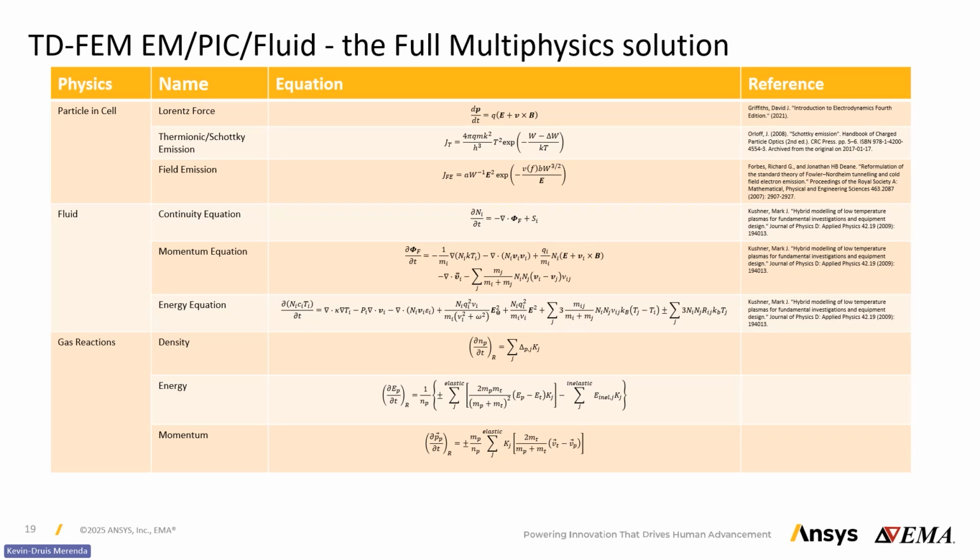So we can do that with the PIC and the fluid solver. The fluid solver is a continuum, so we don't have to worry about that. But having the ability to do a hybrid method like we do here, by having both PIC and fluid, allows us to deal with these transition problems in terms of pressures, where if you want to deal with rarefied gases where CFD is no longer valid, you can use the PIC. If you want to model very highly dynamic electrons, even in a higher density plasma, you can use the PIC and then model everything else, like the ions and the background species, in the fluid solver, and really focus on getting the proper energy distribution for the electrons in the system using the PIC.